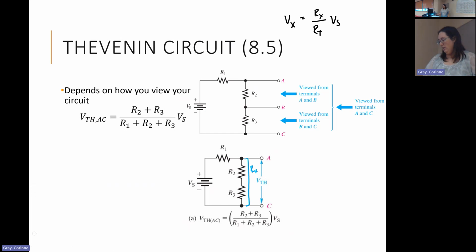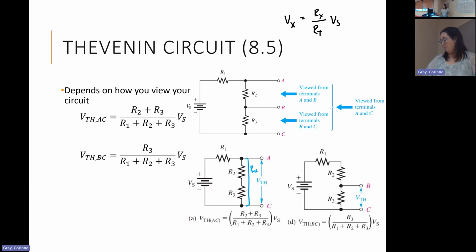If we want it instead to be just one of the resistors, we would again use our voltage divider. Here, this is saying that R3 is equal to the load resistor. So in a circuit, you would see it as RL instead of R3, if that's what you wanted to look for. Then these two together here are RL.